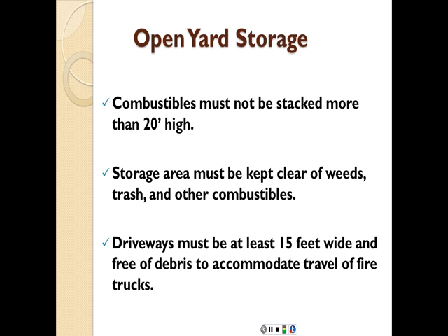In case of open yard storage, combustibles must not be stacked more than 20 feet high. So if you have any combustible material, you're going to stack it on site in open yard storage, not higher than 20 feet. Storage area must be kept clear of weeds, trash, or any other combustibles that can ignite or can help with the ignition, so you want to avoid that. Driveways must be at least 15 feet wide and free of debris to accommodate travel of fire trucks, because you know the fire trucks are much wider than regular vehicles, so you want to allow for at least 15 feet wide access.